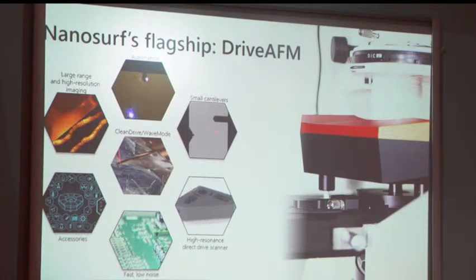Number two, you can use the standard cantilevers that all AFM companies use. You can now also use very small cantilevers to scan fast, so you can take images quite quickly, within a few seconds. Then you have a controller which is the lowest noise controller available in industry. It is a 28-bit controller, with a high resonance scanner which can scan faster, and you have a whole bunch of accessories. And the good thing about the Drive AFM is that it can go from atomic resolution up to a 100 micron area. Any type of resolution you want to get, you can get out of it.